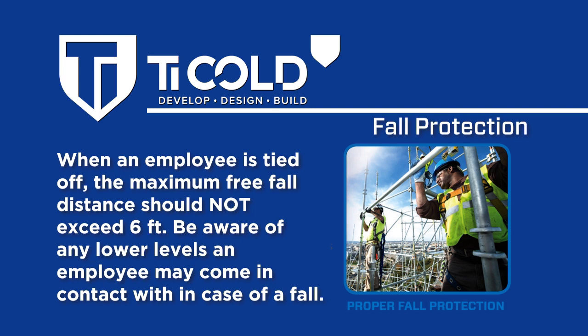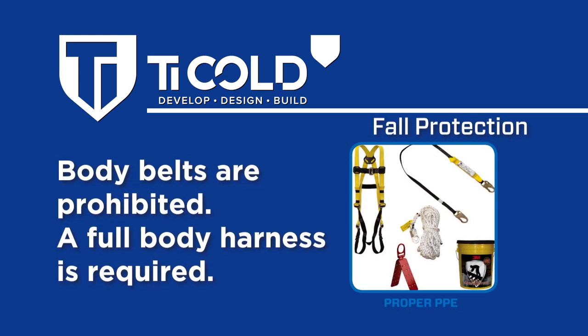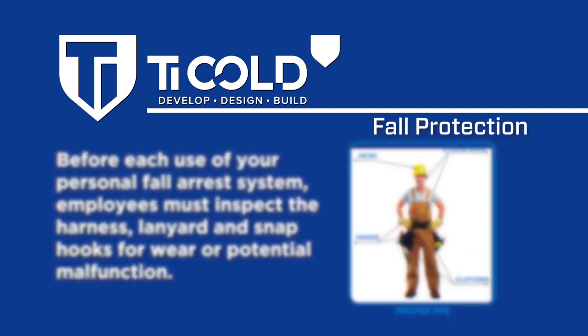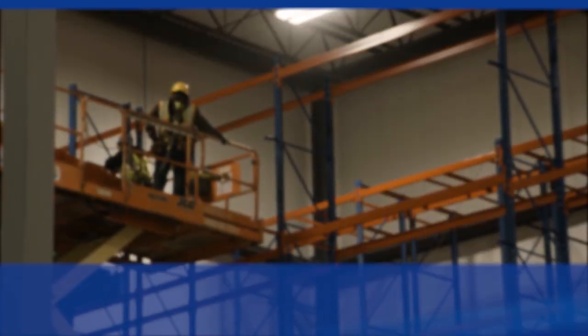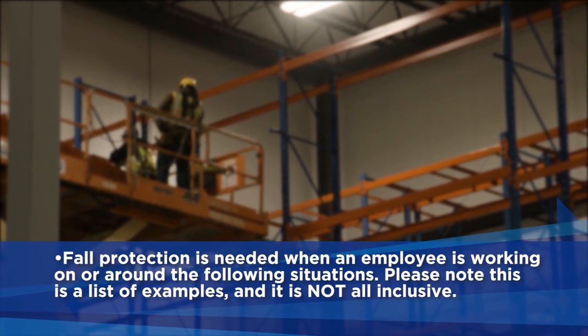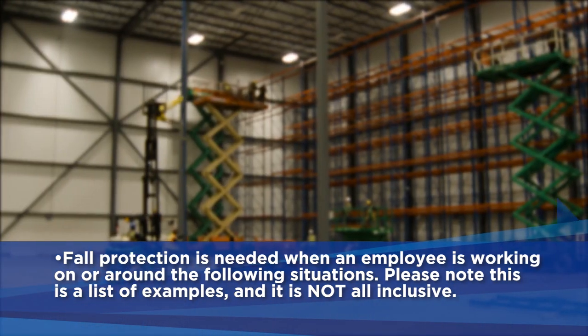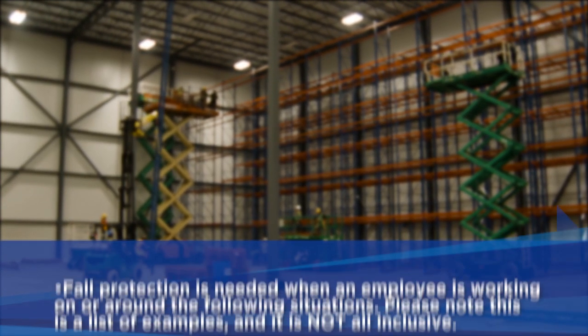Be aware of any lower levels an employee may come in contact with in case of a fall. Body belts are prohibited. A full body harness is required. Before each use of your personal fall arrest system, employees must inspect the harness, lanyard, and snap hooks for wear or potential malfunction. Fall protection is needed when an employee is working on or around the following situations. Please note, this is a list of examples, and it is not all-inclusive.